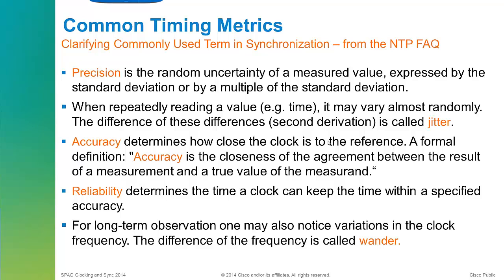Okay, so some of the terms that we need to talk about. Probably the most important two are jitter and wander. We've already seen a little bit how jitter works. Jitter is almost a short-term random variation. When we saw it in a packet-based network, packet delay variation was holding up various packets, and that introduced jitter into our network, into our frequency recovery. Similarly, when we have circuits on a physical wire, we get jitter caused by reflections and crosstalk and stuff.